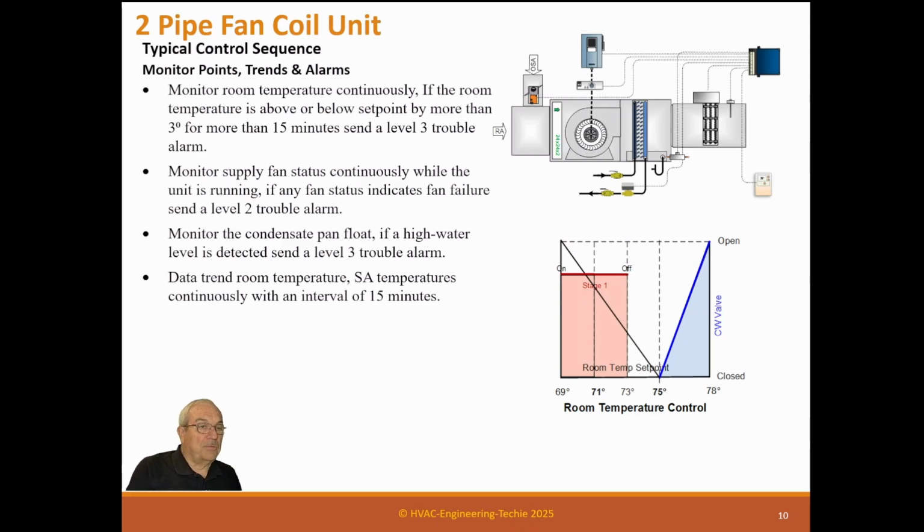Data trend room temperature and supplier temperatures continuously with an interval of 15 minutes. So we want to know what the room temperature and the supplier temperature is, as a tool for the operators to use. Data run time of the motor, resettable by operators for maintenance.